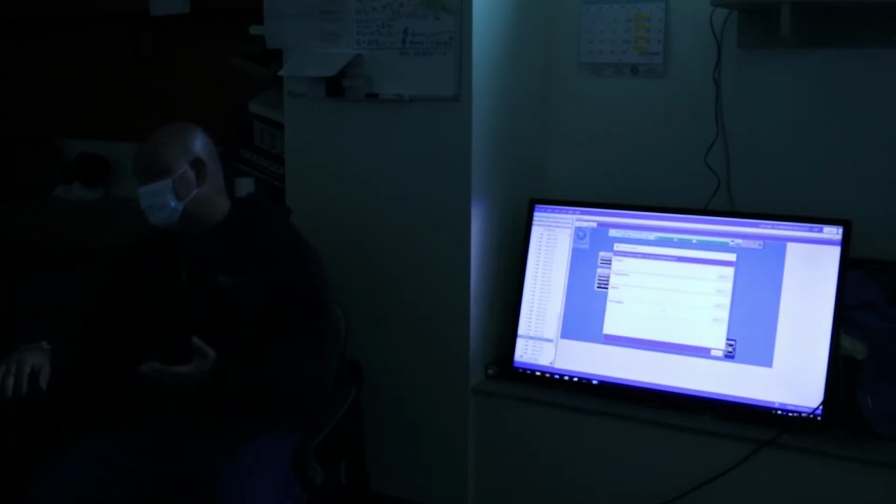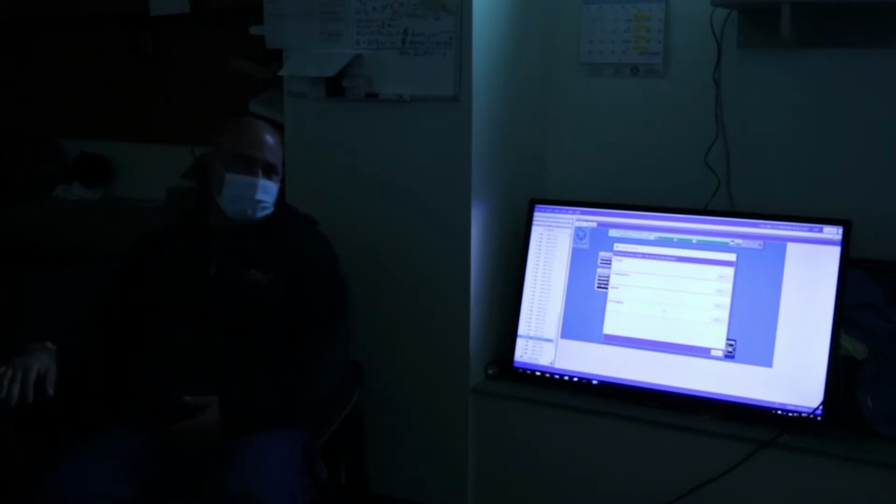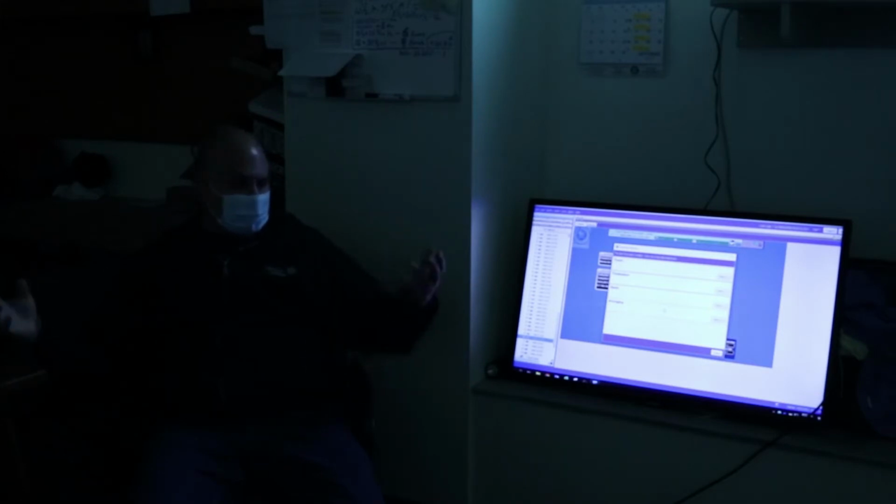From that right click, you can also add, okay, I showed you the trend, I showed you the alarm. You can do totalization, which is like a runtime on how long something is on. Or you could do averaging, where you could see what the average is over the course of so much time. Let's see the averaging.